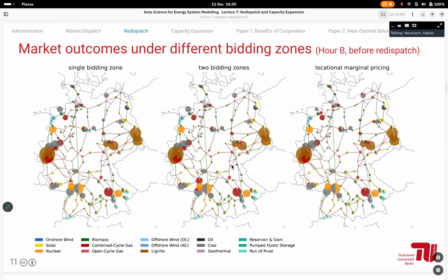So what changes now from modeling electricity markets with existing capacities to the scope of system planning, investment planning, or capacity expansion? Various different terms are thrown around for the same type of problem. So far, in the optimization problems, the decision variables, or degrees of freedom, in the short-term perspective were the dispatch of the power plants, the operation of the storage units, or the curtailment of the renewables. And we basically promote now the limits of these dispatch decisions to decision variables.